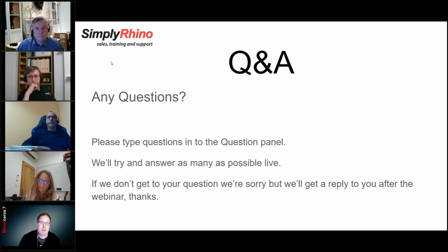If it's a NURBS already, then changing the mesh settings, and maybe even changing the mesh settings just for that object, could make a really big difference. But if it's already a mesh, what I do is use QuadRemesh, convert it to a SubD, and now I have flexibility to adjust the render mesh that's going to be delivered to the renderer. That's one of the advantages of converting that dense mesh back up to a SubD and maybe even a NURBS.